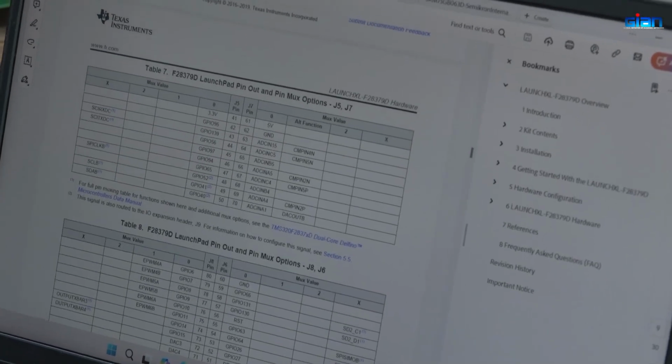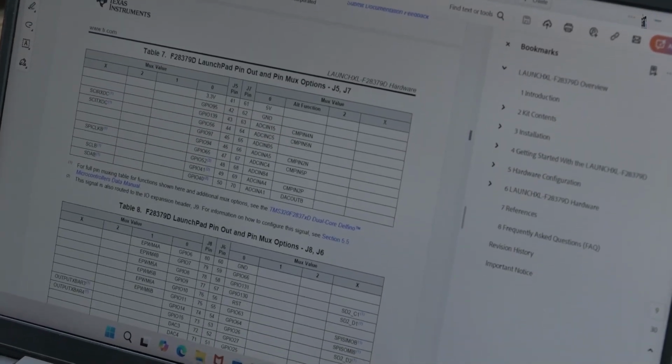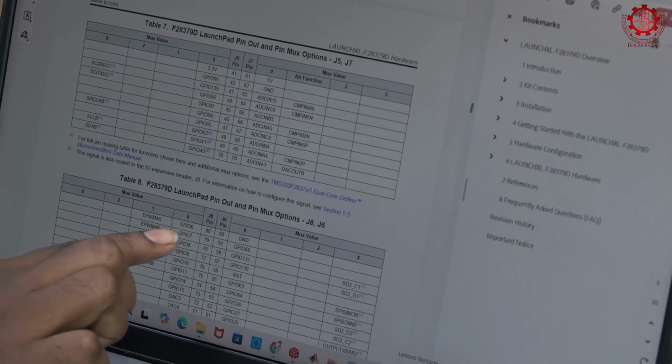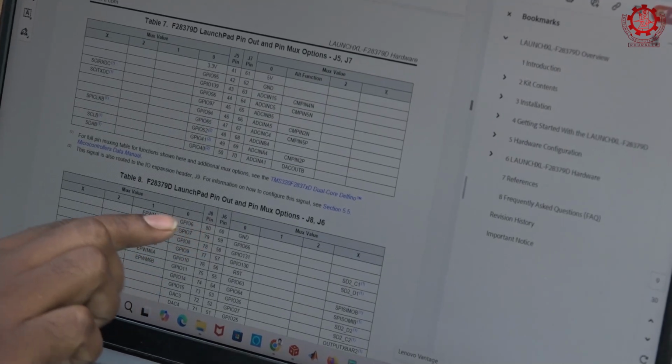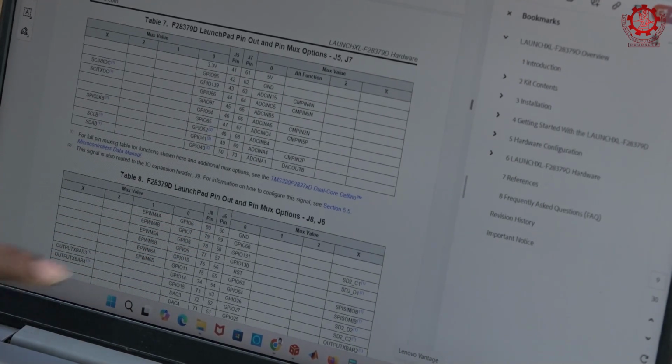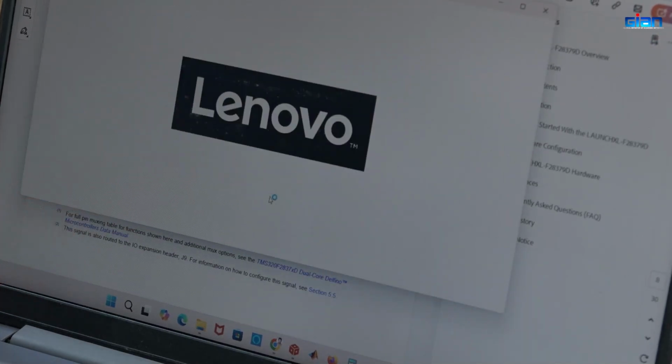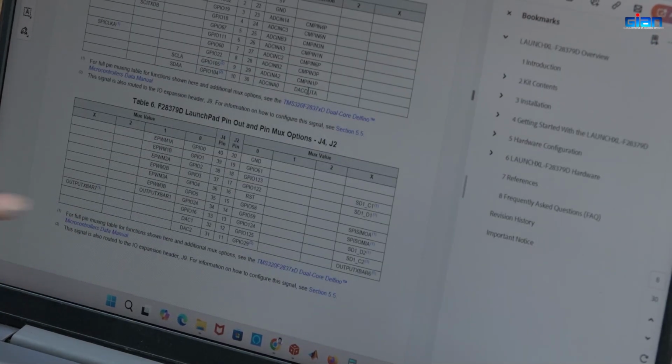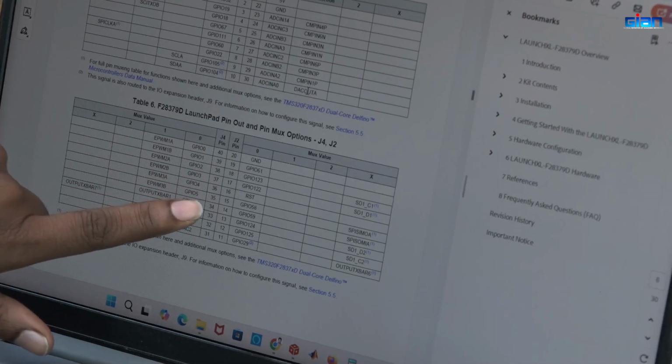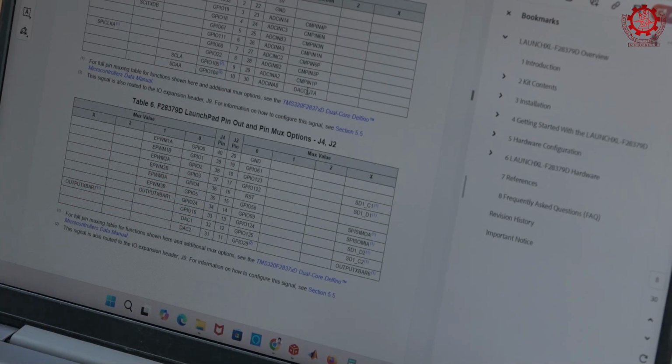So for that I used 4 EPWM modules, and I also use EPWM4A, which is GPIO 06, pin 80. So I am using pin 80, pin 40, pin 38 and pin 36. These 4 pins I am using to generate the pulses to give to this driver circuit.